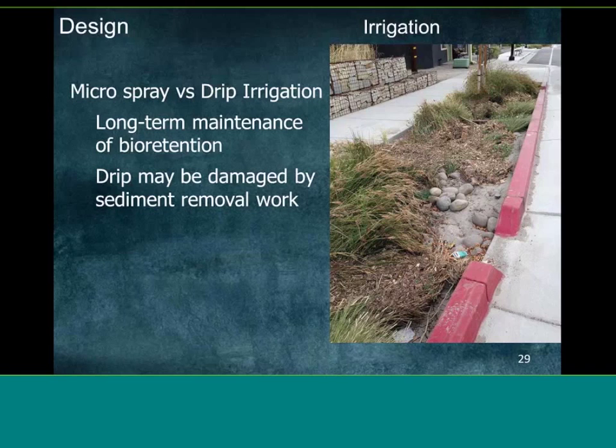But it's interesting when the project was hit by an extremely large storm in the summer when it wasn't expected, a lot of sediment entered the bioretention areas, and they'll have to be removed manually, with shovels. They're going to be in there walking all over that place. And I'm so thankful that it isn't a drip system, because I can't imagine the kind of damage that would have been done. And then you're either seeing leaks down the road that are wasting more water, or the municipalities having to repair a system. So I think that's been a good lesson learned for me.